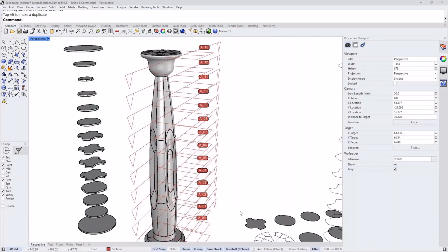You can export it with your drawing, if that makes sense. So that's another use case for it. Is the distinction kind of clear? You can think of one of them as dynamic Make2D and the other as section and contour commands, but with history enabled. Does that make sense?